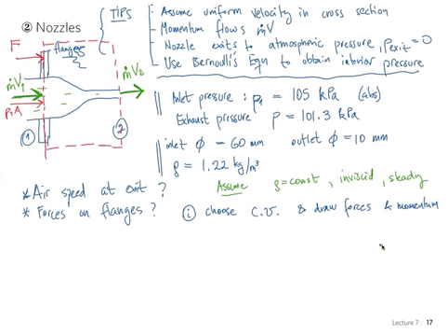So I'll draw forces and momentum and choose my control volume. So momentum inflow and outflow in the, say, x direction. Let's call this x direction. And force due to pressure and the forces at the flanges. We've set up the problem now.